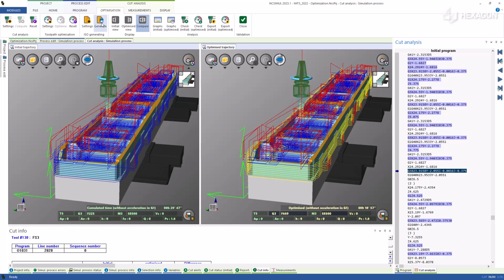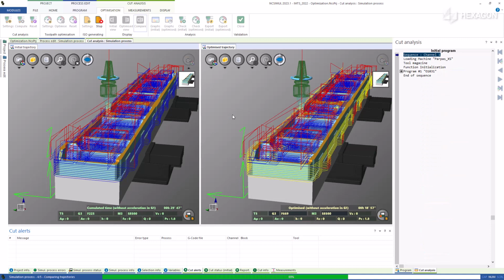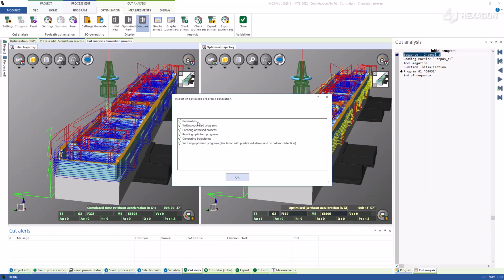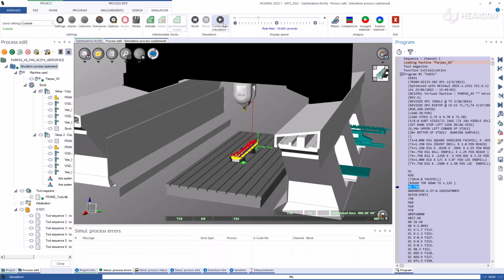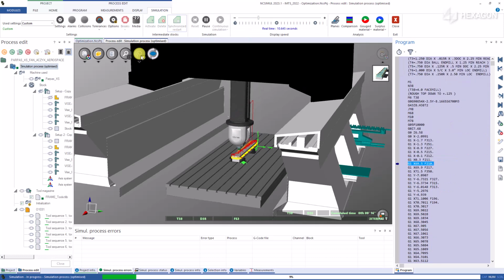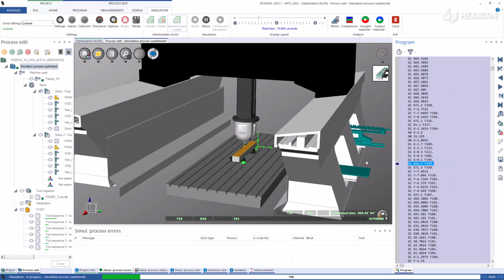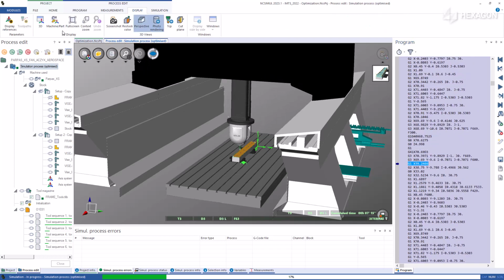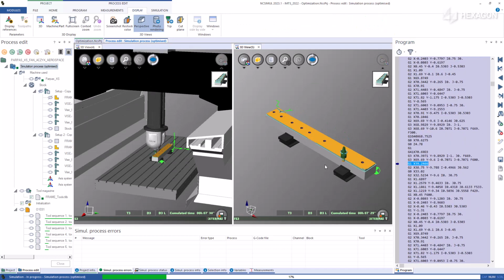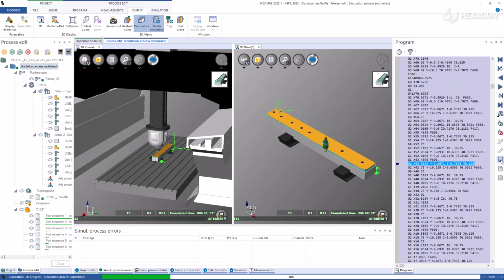Simply hit Generate and it will create a copy of the new G-code into the optimization folder, retaining your old code in the tapes folder and creating a new simulation environment to do a final test with the new parameters. To finalize your process, hit Save As, and that G-code can be pushed to the shop floor for production, knowing that you have a collision-free program that has a significant reduction in cycle time with a smoother and more consistent engagement to increase all tool lives.